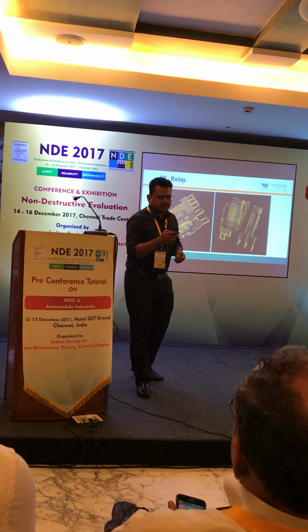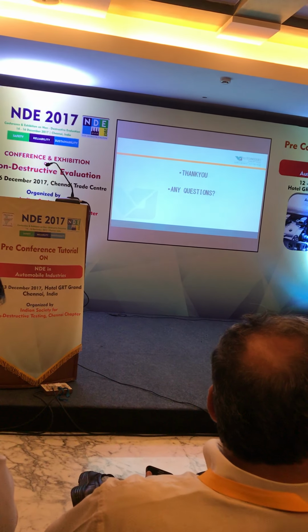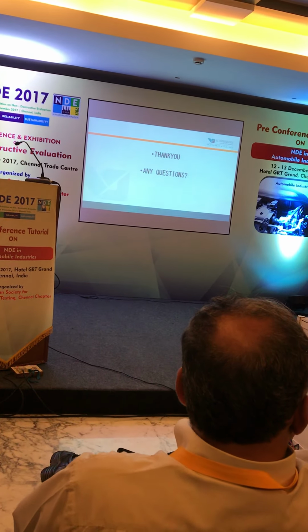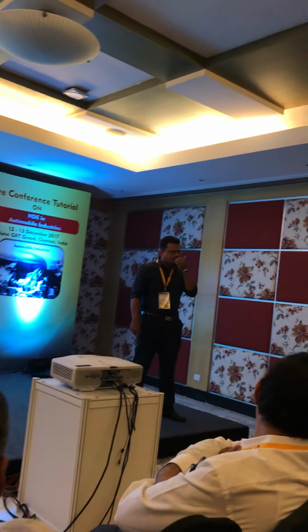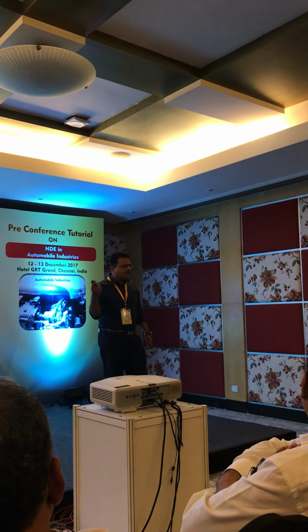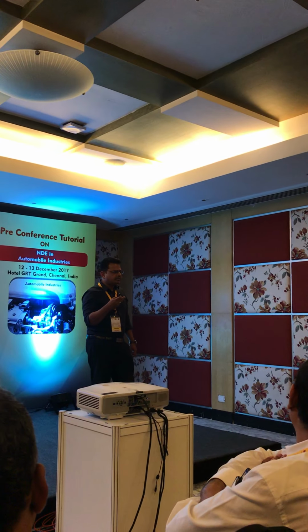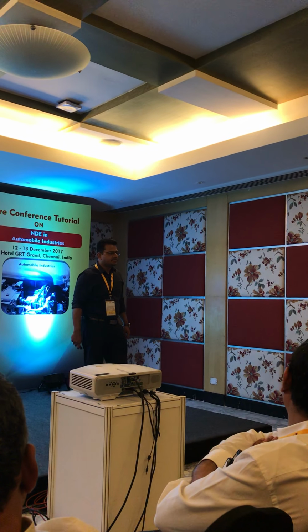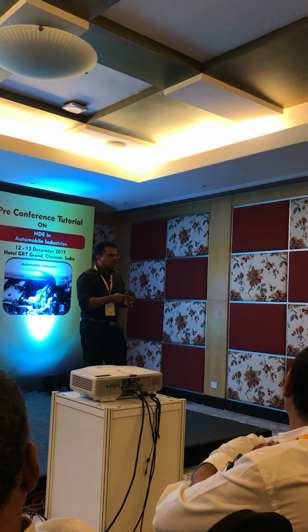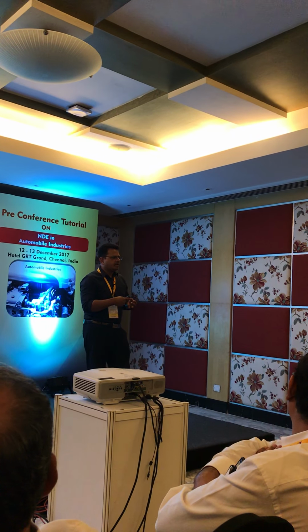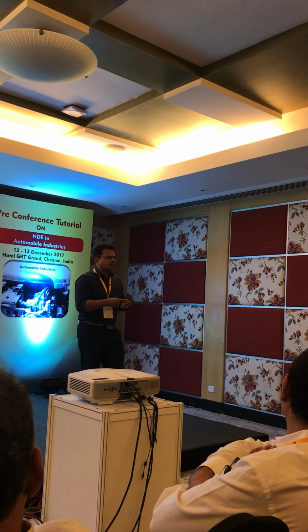Any questions you have regarding the ADR? For ADR, if you are scanning thick parts or dense metal parts, there are chances that noise may occur in the image. So how does it differentiate a defect from noise? See, before sending it to the ADR, we take an image and check that the captured image doesn't have noise. So we play around with the kV and the mA, and make sure we don't have noise. The later images are sent to the ADR.